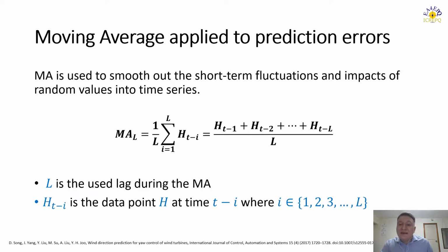Observing the data, we see and know that several variables make the data take a sinusoidal behavior, so we cannot clearly see the trend of the data. And then it could be kind of difficult to detect a fault. Moving average appears instead as a strategy to extract the trend of a time series, computing the mean of shorter and successive time series. The equation in this slide computes those time series means or averages, in which we must define the temporal window or the lag. For this case, we set 30 minutes as the lag.